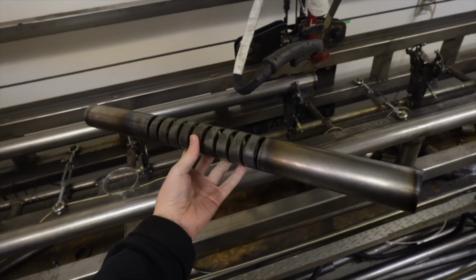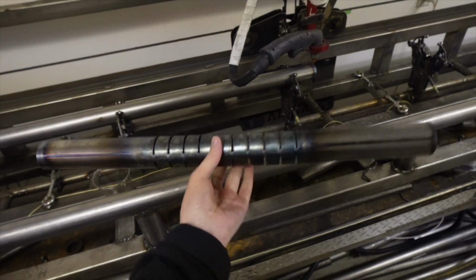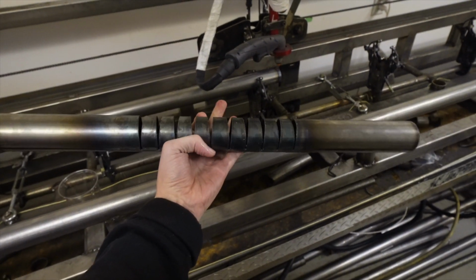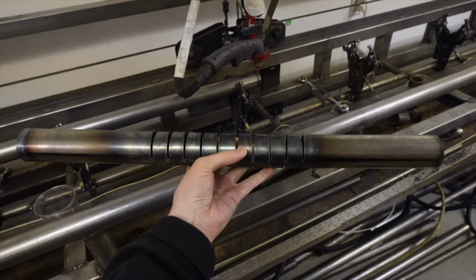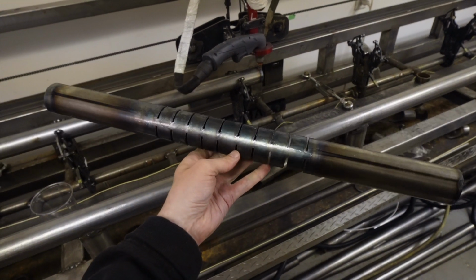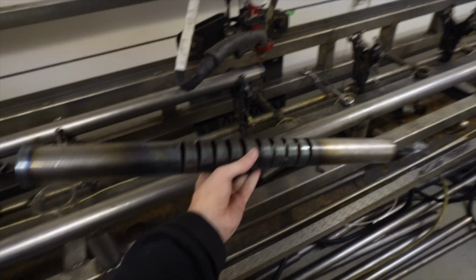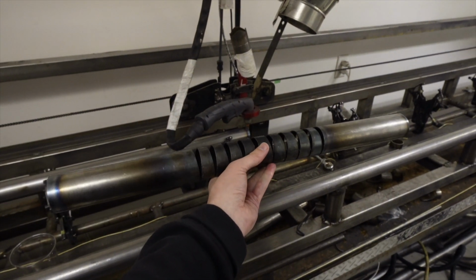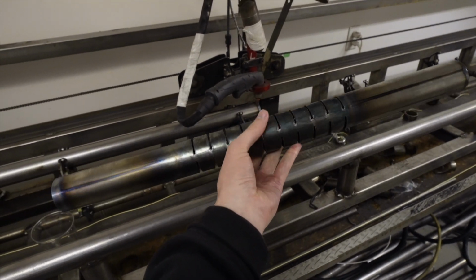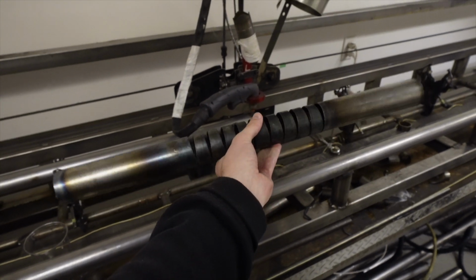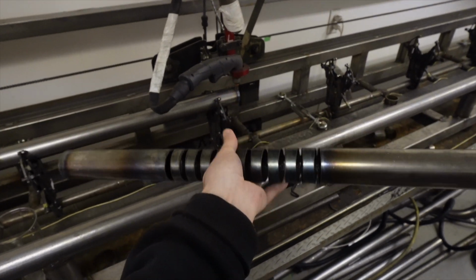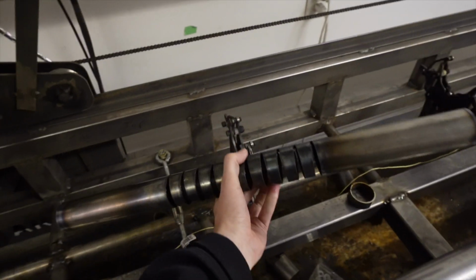Here's the test cut without being bent. So this is an experiment. This is a 90-degree bend with a 4-inch bend radius. And I'm gonna have to experiment with the torch kerf width and the gap, the uncut portion. There's probably gonna be an issue cutting long sections of tube with multiple bends in that there's not a lot of structure left on the tube to hold the remaining section. So after several cuts in a long tube, it may twist or these gaps may bind in the bearings.